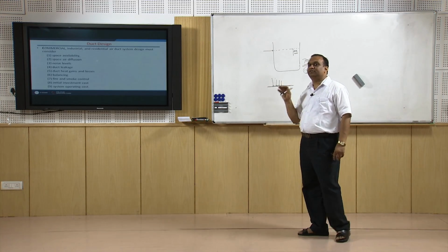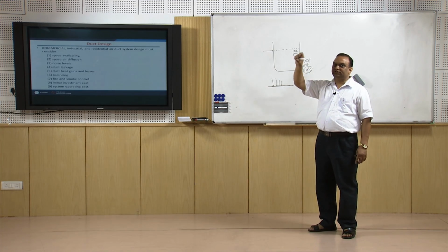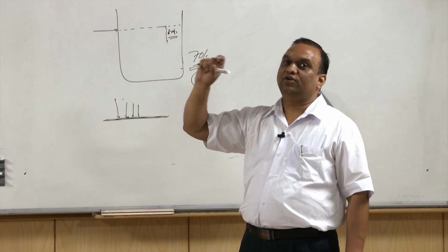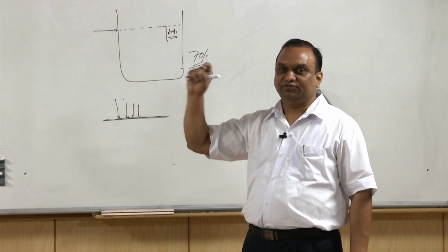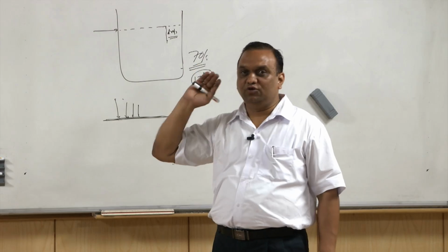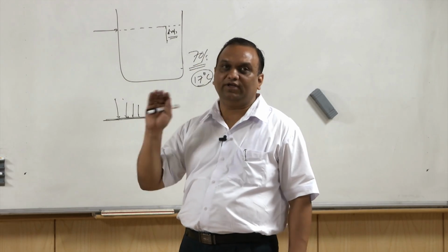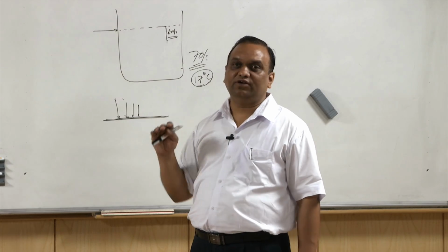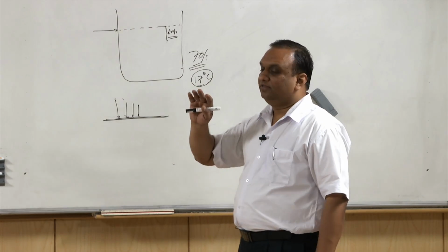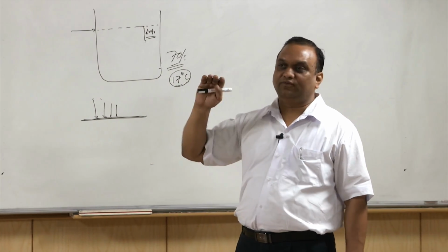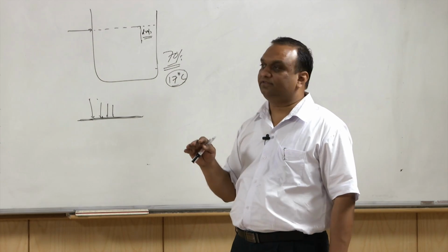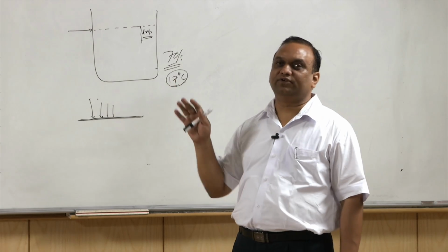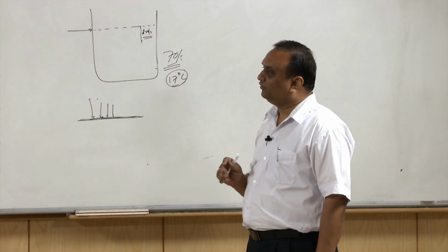You must have seen in some buildings discolored walls in the vicinity of the duct. That is due to sweating of the duct. The ducts were not properly insulated. That is why when hot and humid air came into contact with the duct, condensation took place, and the water vapor condensed on the duct surface, subsequently discoloring the wall. You must have observed such things in many buildings.